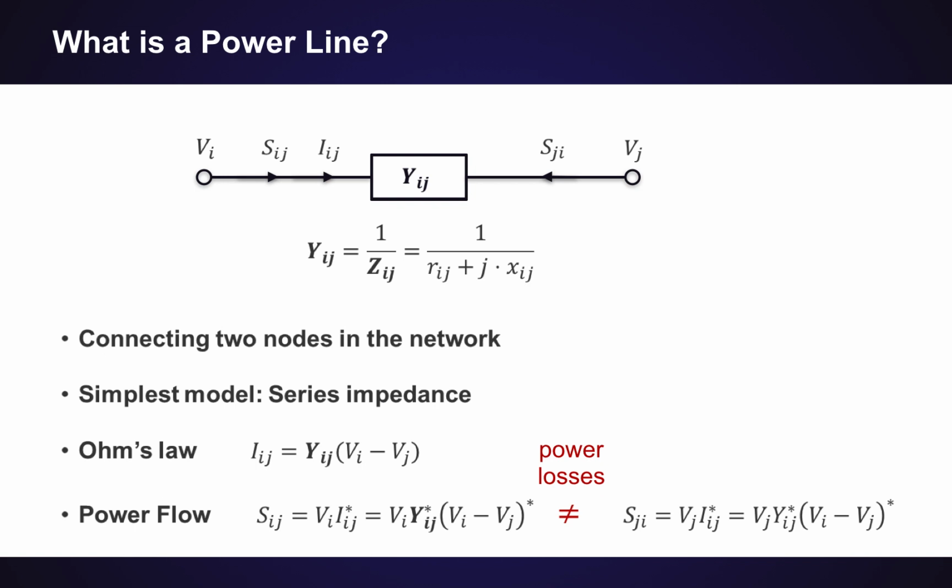I think it's also interesting to note here that you actually need to measure either the current or the power on, say, the I side of the line or the J side of the line. In a lot of CS applications, you just need one variable to represent the flow on the line. But in power systems, there really is a difference between what's happening very close to one bus versus the other. Yeah, so it is important to take this into account.